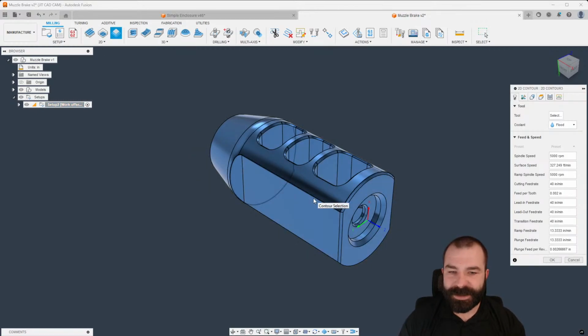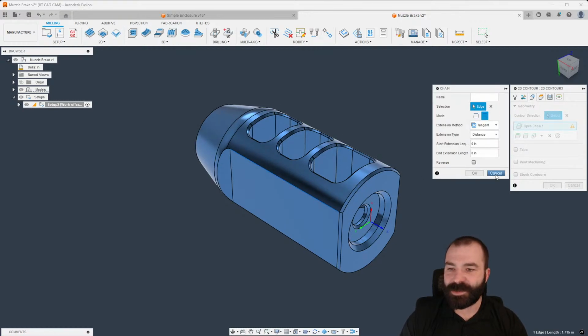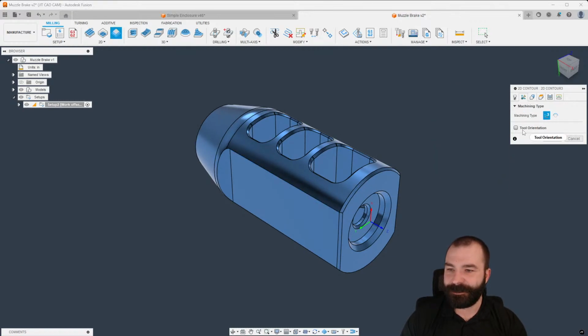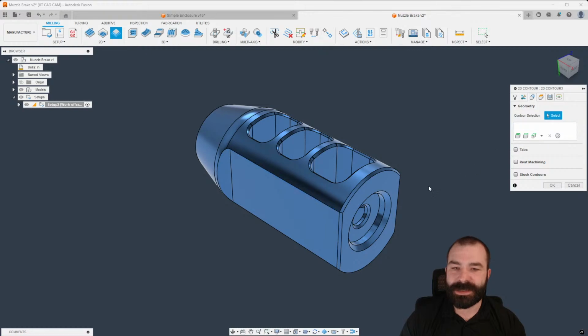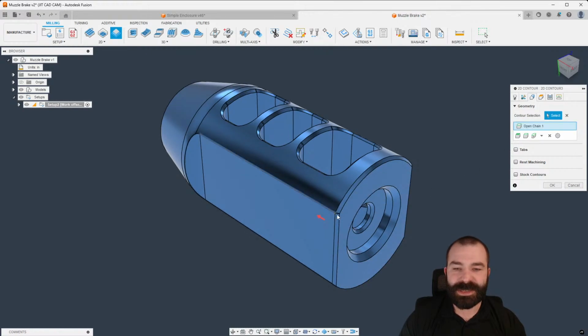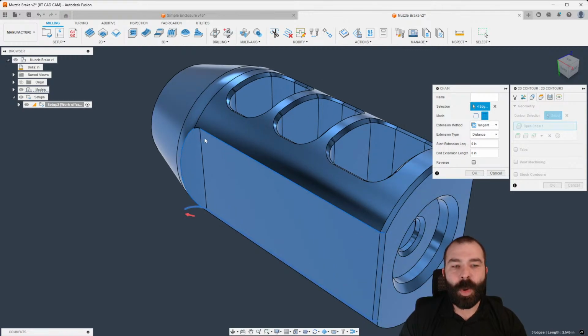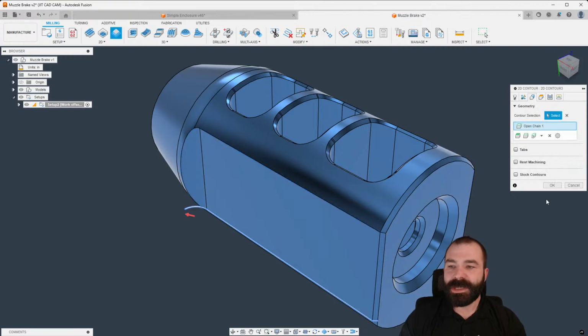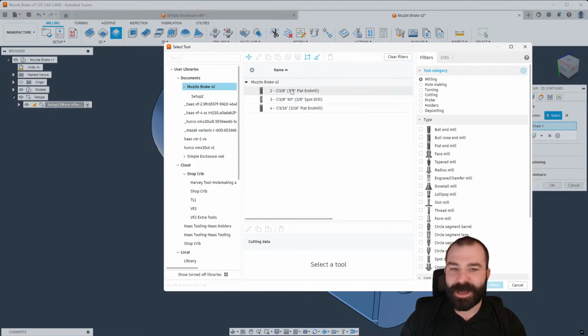Now, if you have done this, you already know where this is going to end up. As you can see, we actually need to set tool orientation, so I'm getting ahead of myself. Let's go ahead and get that tool orientation going. You want Z-axis up and down. And then the chain that I want to use is going to be these edges here. Now, for most of you, you may pick the lower edges or the upper edges. What I want to show you is, if you notice, this chain down here on the backside is actually doubling back on itself. So sometimes when you're trying to machine something like this, it will affect kind of everything you're doing.